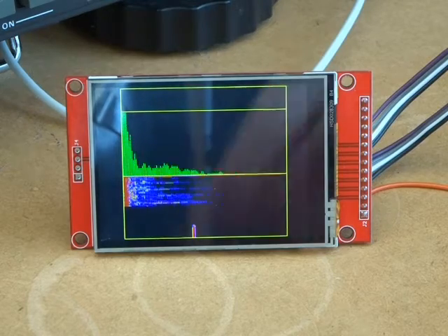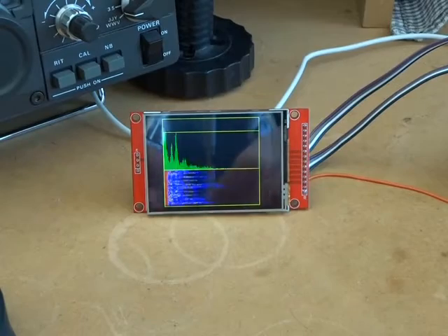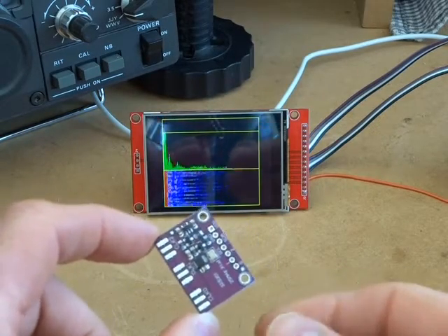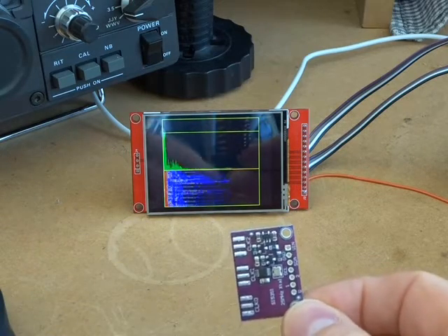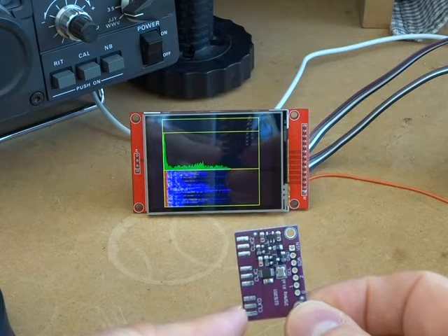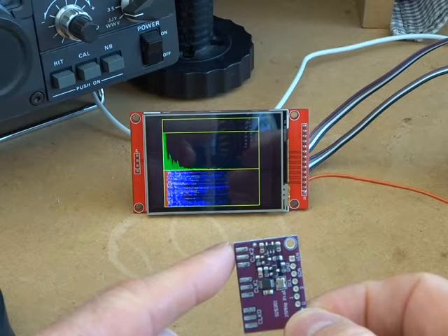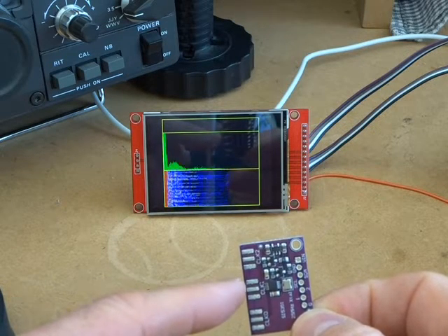So what I've decided to do, and I'll come to that again at the end when we start thinking about the way ahead, is I've been using these quite a bit. This is the SI5351 breakout board. Typically clock 0 is the variable frequency oscillator, and clock 2 is the beat frequency oscillator. There is a spare one there, obviously clock 1 is spare,